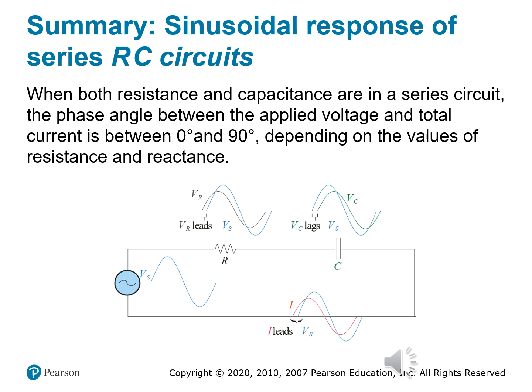V sub C slightly behind V sub S, and V sub R aligned with the current. And this phase relationship is a diagnostic fingerprint, and it's how you know you have capacitance in play within the circuit. But how much phase shift?